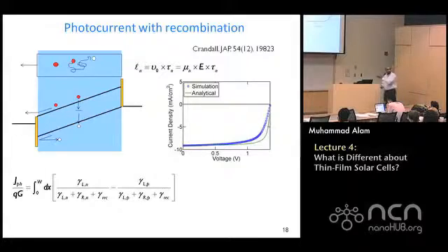Okay, again, would this formula work? Well, generally it should work, because you can see how this formula should work. Gamma Lp is 0, because I have put a blocking layer. Gamma Rn is also 0, because I have put a blocking layer. So that's not going to go anywhere. Now the fraction of electrons that is injected at a given point and comes out, going through these recombination processes, is this ratio: gamma Ln divided by gamma Ln plus gamma R.